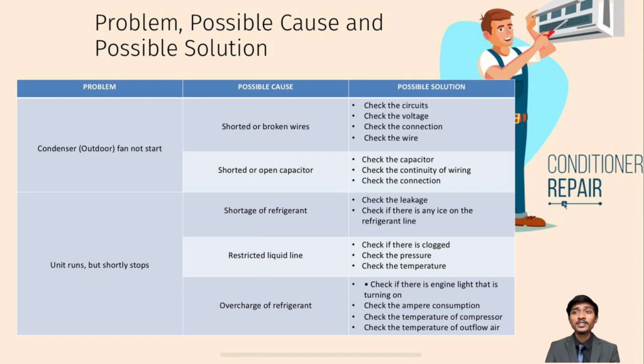For overcharge of refrigerant, the possible solution is to check if there is an engine light turning on, then check the ampere consumption, check the temperature of the compressor, and last, check the temperature of the outflow air.